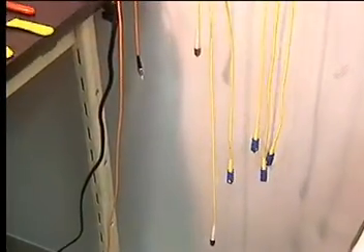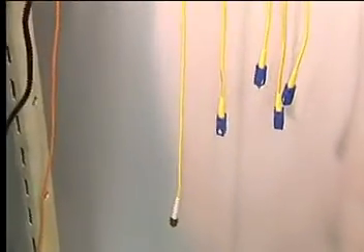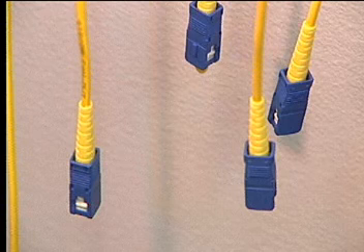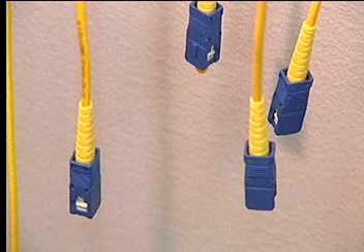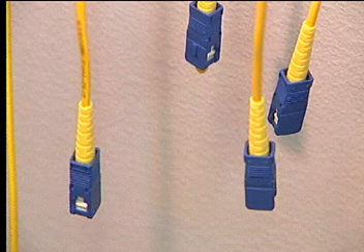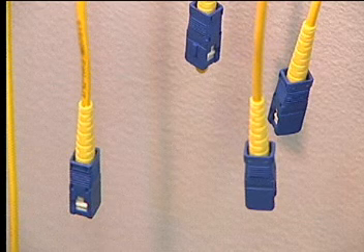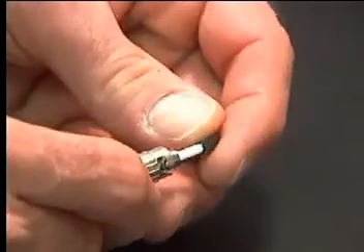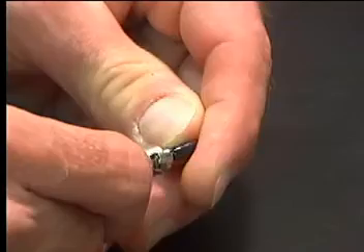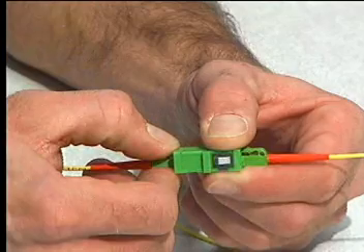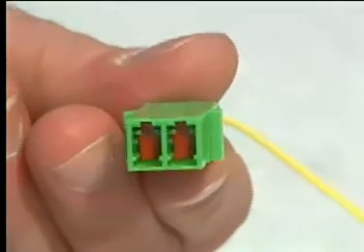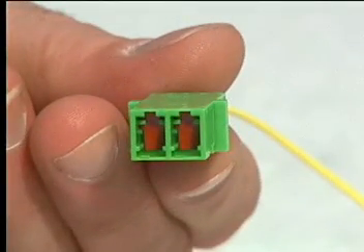Never allow connectors to come in contact with any surface when not mated. While temporarily disconnected, hang the connector over a table edge or other convenient support to allow it to be suspended in mid-air. Be sure the connector cannot collide with other connectors or with any other surface while suspended. When disconnected for extended periods, cap the connector ferrule to prevent contamination and scratches. Some of the more recent connector designs feature internal automatic dust caps that deploy the instant the connector is unmated.